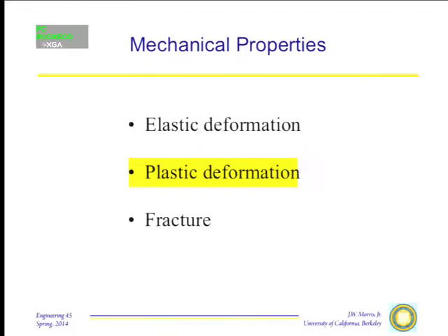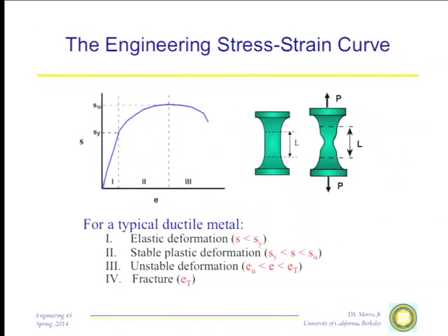All right, we're doing mechanical properties, and systematically we talked about elastic deformation. Today we're going to focus on plastic deformation, and then we'll turn to fracture and how things break. Just to remember, you can summarize the important mechanical properties of a material in a tensile test, in which the engineering stress-strain curve comes out looking something like this.